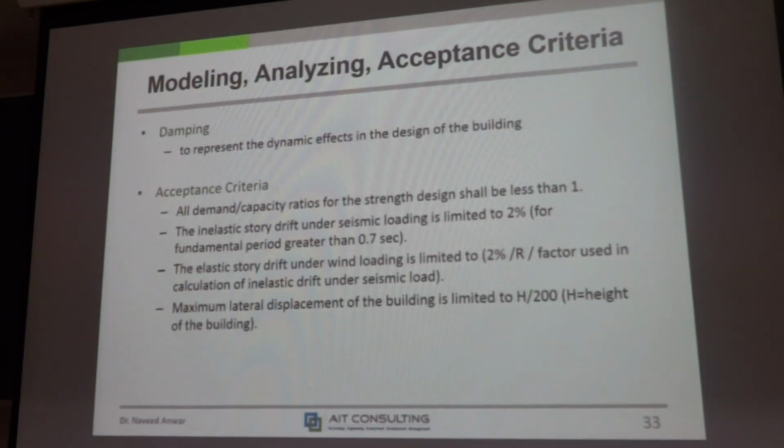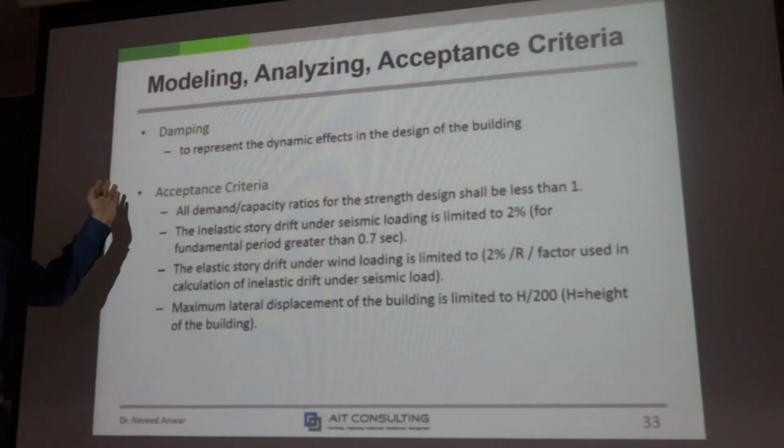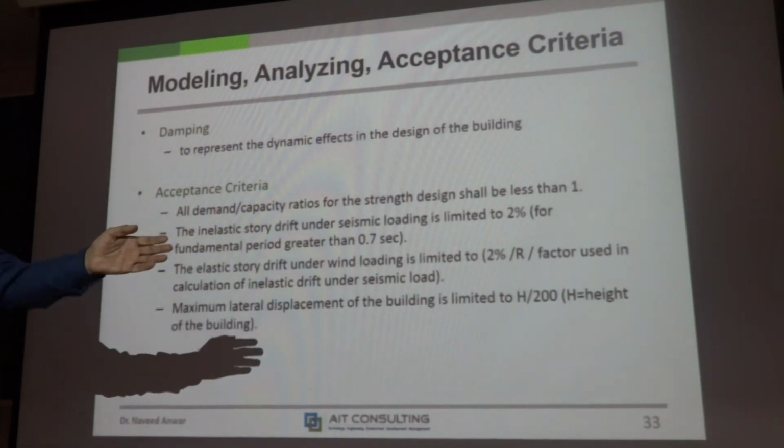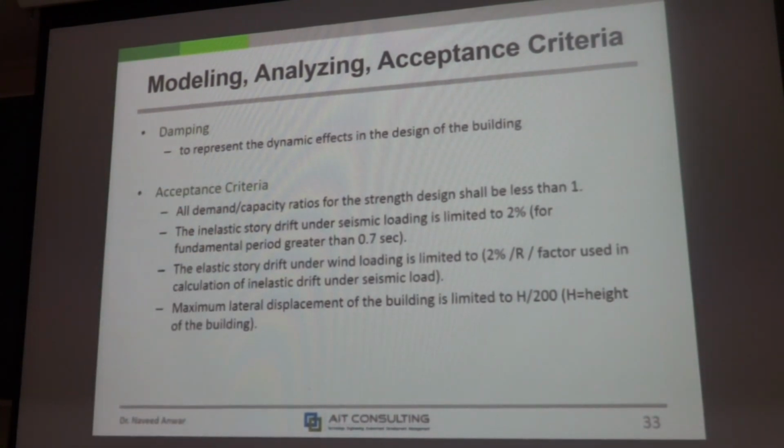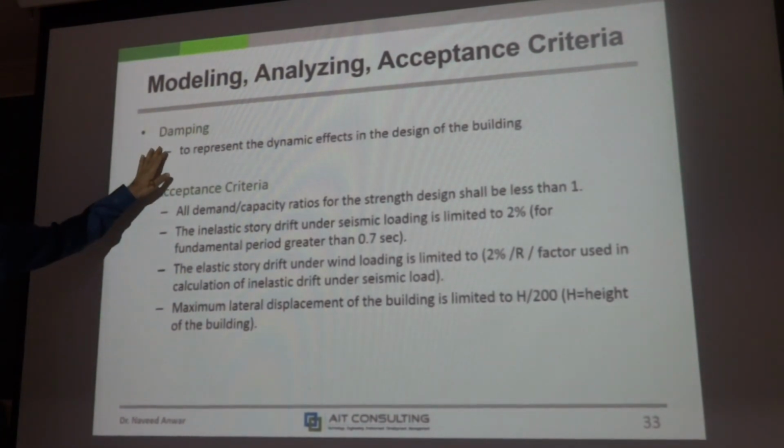Damping. How much damping to use? 5%, 2%, 1%, 10%. What is damping? Where did it come from? How can we increase it? How can we decrease it? How can we play around with damping to change our results? But you need to specify what damping I'm going to use and why.